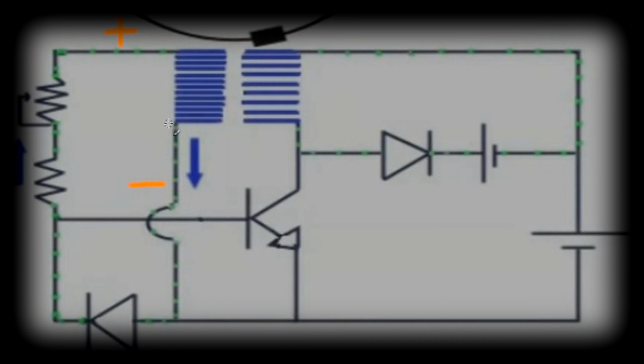So the magnet and its magnetic field, placing field on the trigger winding, it will place it with this polarity, so that plus 2 to 5 volts will go through here, hit the base with a positive signal, and the minus 2 to 5 volts, whatever the magnet on the rotor produces on the trigger winding, will go down this way to the emitter.